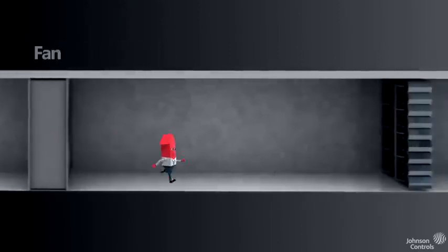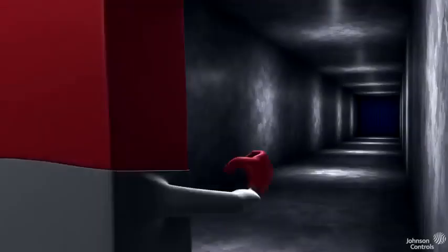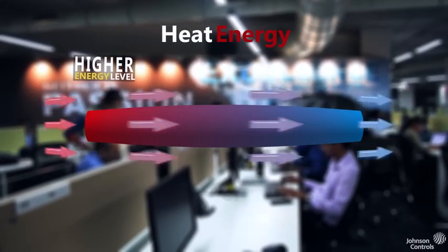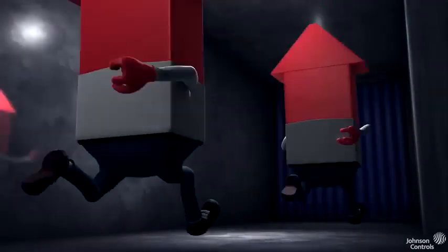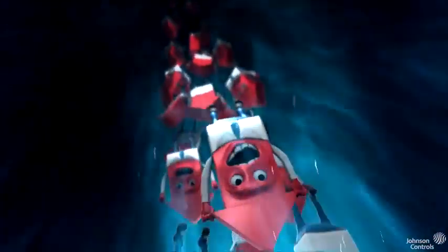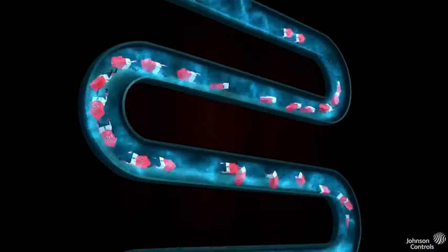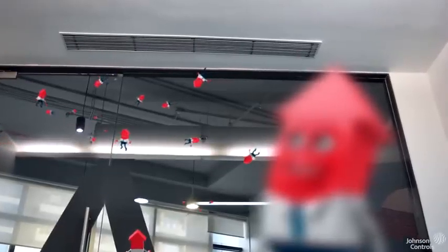After whizzing around in the fan and zipping through a bank of filters, Mr. BTU eventually finds himself traveling across a cold, chilled water coil. Remembering that heat always travels from a higher energy level to a lower energy level, he now enters the chilled water through the walls of the cooling coil. With all of his friends, the effect is to raise the temperature of the chilled water, and heat is removed from the airstream, cooling it down. This air returns to the office at this lower temperature, ready to move more BTUs.